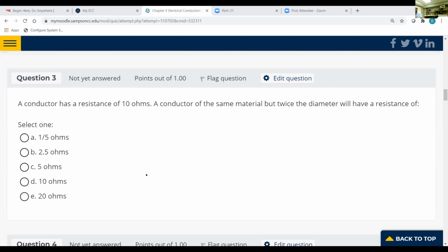Let's say this. For every thousandth of an inch that you have, you have a diameter of 1,000th, that's considered to be 1 mil. Now, if I have 10 thousandths of an inch, which is the same thing as 100th, then I actually have 10 mils, don't I? This would equal 10 mils when you convert diameter to mils.